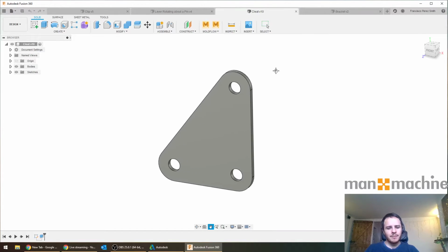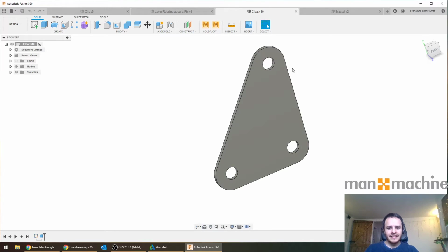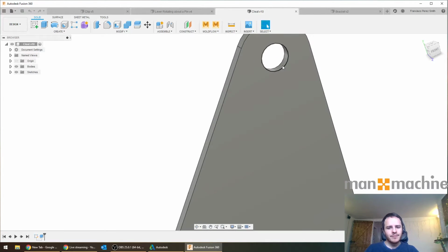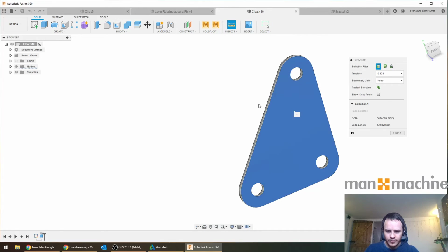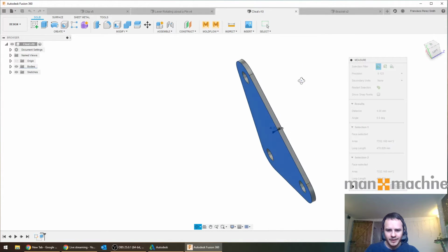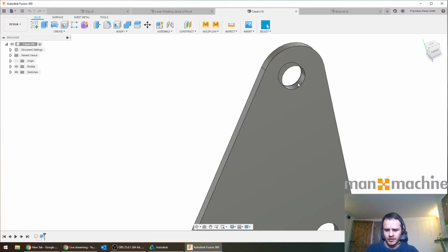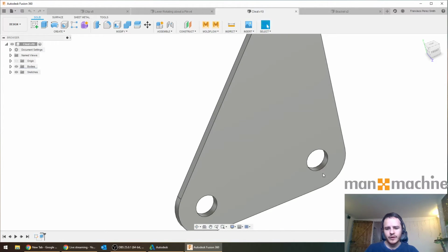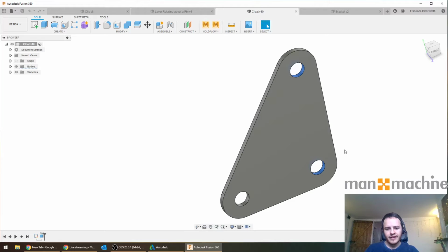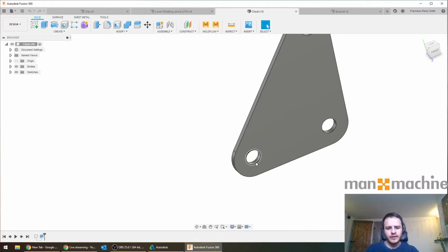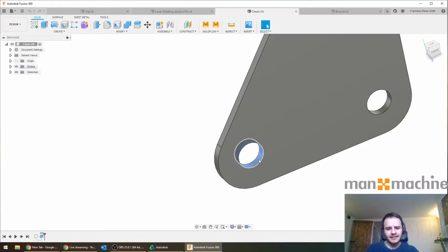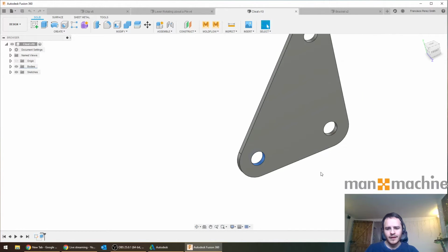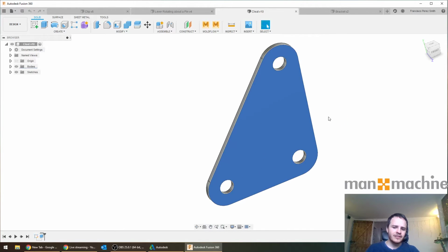We're going to have a look at a practical design problem. Here we have a cleat, and it's going to be held in an interesting way. We'll quickly have a look, and we'll see that the cleat is 4 millimeters thick, and it's going to be fixed with 2 pin joints that will connect here and here, and it's going to be loaded with 6,000 newtons acting down on this pinhole. It's also going to be prevented from wobbling from side to side with a frictionless constraint on the side. Whether that's realistic is very dependent on the problem, but we'll have a look at it anyway.